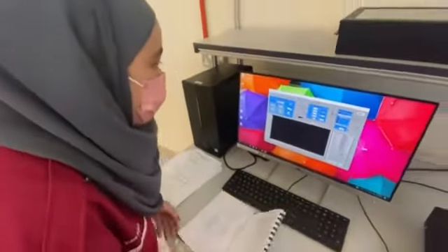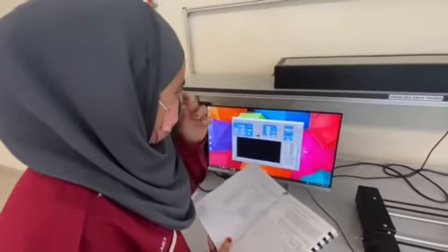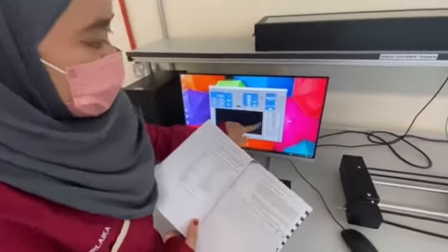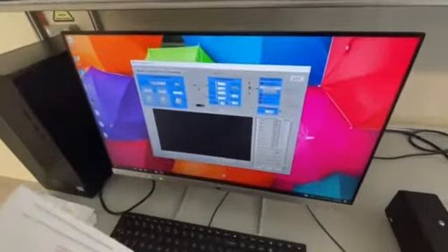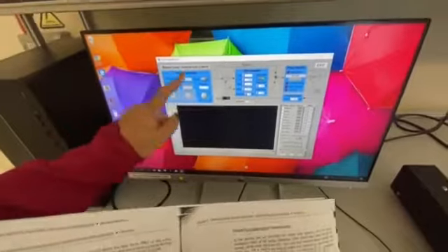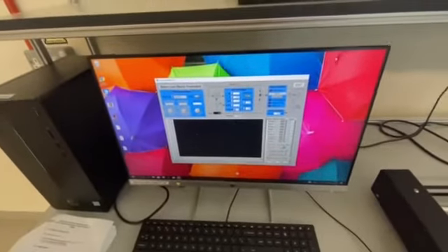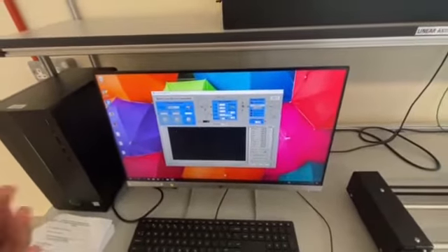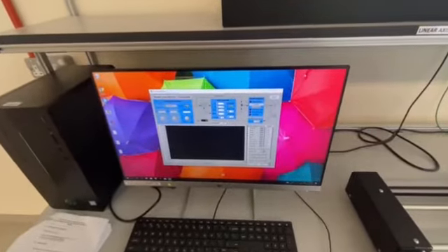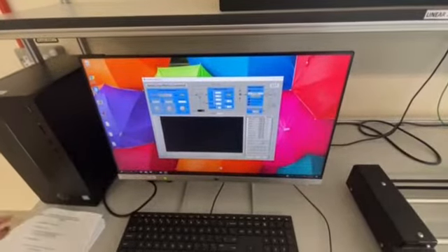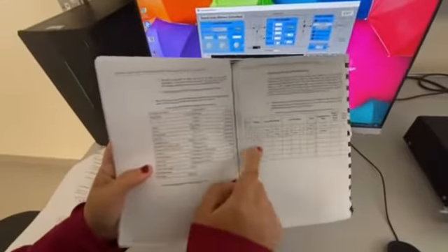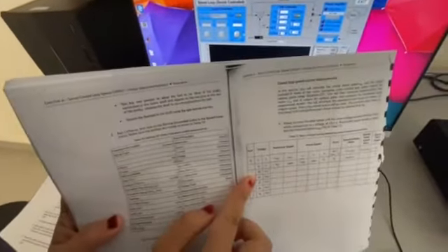Firstly, for conducting this experiment, we have to set all these controls according to this table. We have to uncheck the reference, speed, and current. We have to follow all of this. The next step is to turn on the power and set the offset by following the table given. This is the voltage. We have to set the KP for the voltage.